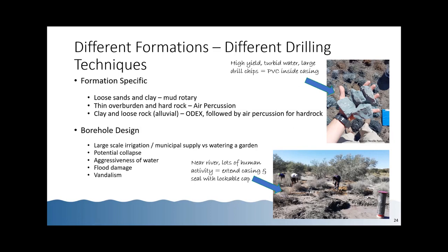Then in the bottom right picture here, you can see the guys cleaning up a site. This is in a river bend almost, or a paleo channel where water used to flow. And here we need to make that borehole as visible as possible, so you can find it easily, obviously. Also, should that flood come, that 1 in a 100-year flood, you've still got the casing above the surface, and you've got no potential contamination occurring from flood water going into your hole.